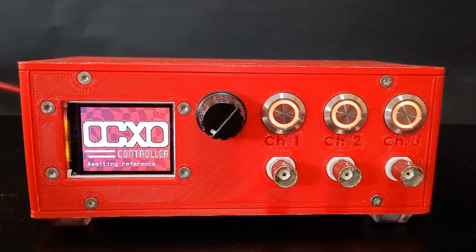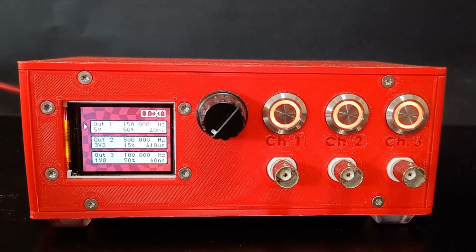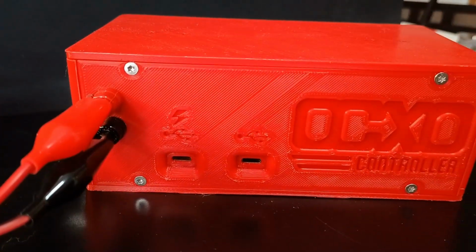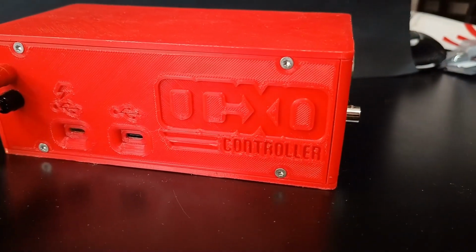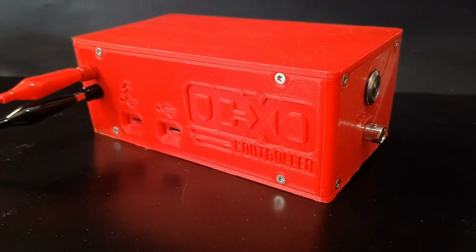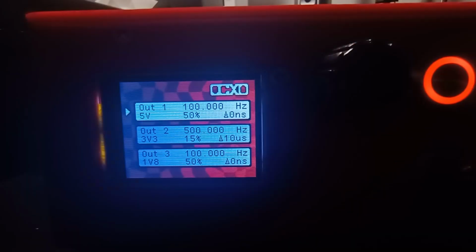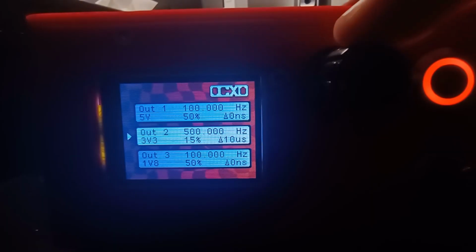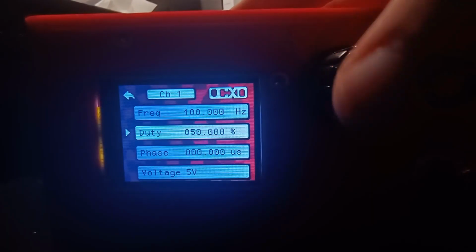An oscillator is an essential electronic component used to generate periodic pulses. These pulses are used in a myriad of ways in electronics. For example, they can be used as the clock signal for a CPU or a microcontroller. On each pulse, the CPU may fetch data from memory, run an instruction, write to memory. All these sequential operations advance at a rhythm set by the clock signal.